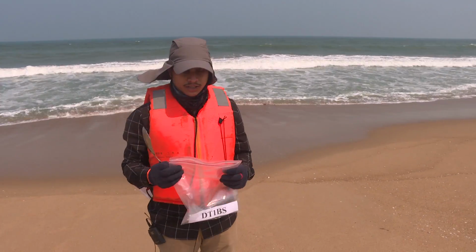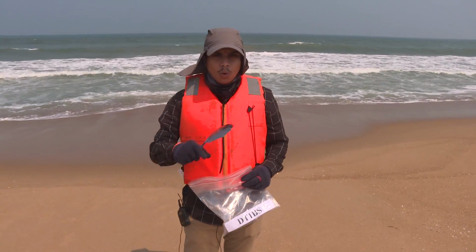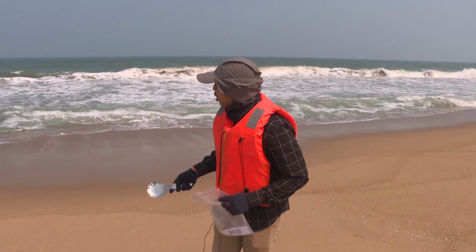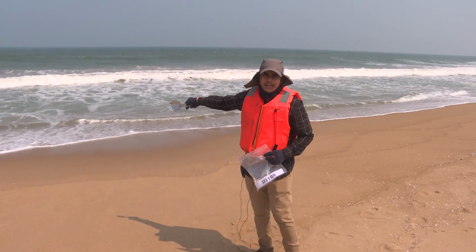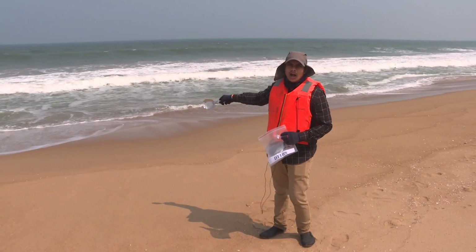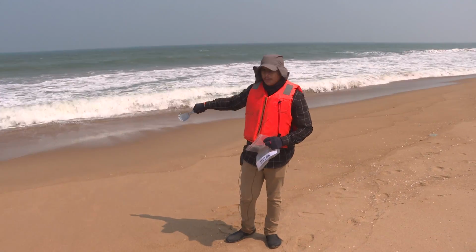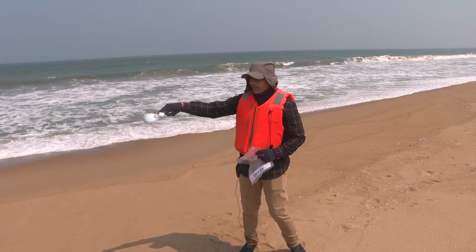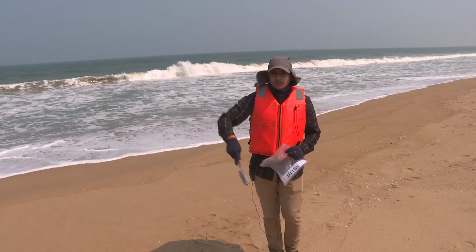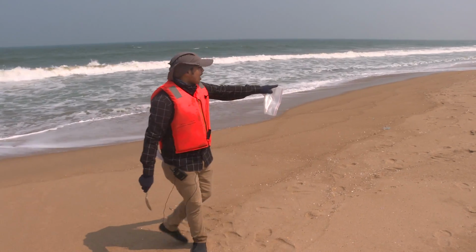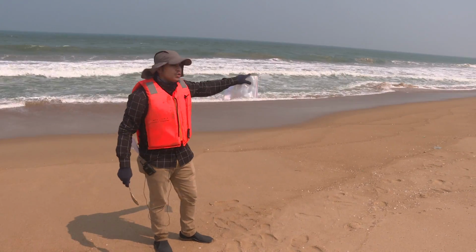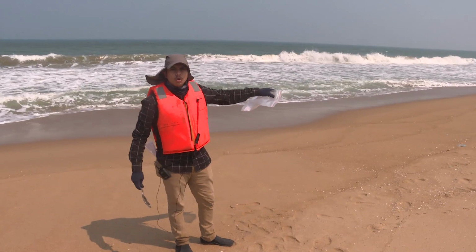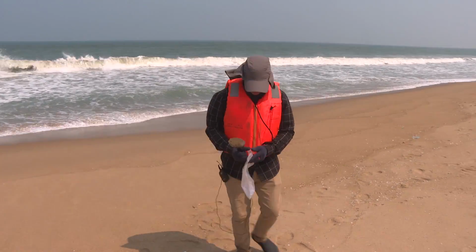At each predefined transect, we will be collecting two samples, one at the foreshore and the other at the surf zone. You can see on the beach where the wave starts breaking, that's called the surf zone, and we'll be taking a sediment sample there, and the other sample at the berm. You can see the berm in the shoreline. You can actually see the variations along the berm. It starts descending so fast, and that's the mark for us to point the zone.